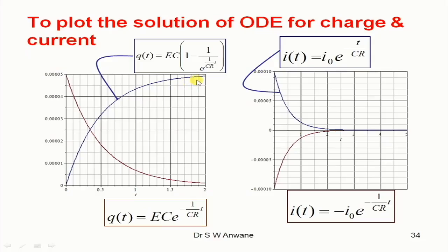Now here I have tried to show you transient current in the left hand side graph. This is rising transient current and this is decaying transient current, whereas in the next diagram we have transient current where the y parameter is a little different, obtained from the derivative as in the earlier slide, and during discharge current is flowing in the opposite direction. So this blue graph is for charging and the red graph is for discharge. This makes complete sense of the flow of current as well as transient charge in an RC circuit.